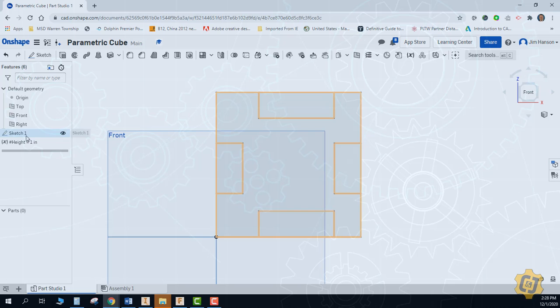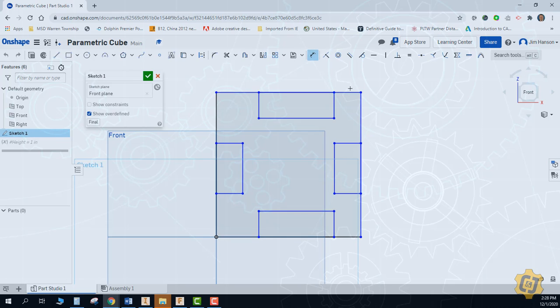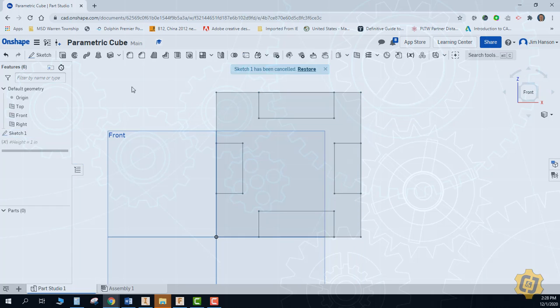The problem is, as I go back into the sketch and try to put on a dimension for the height, it's not usable. It's not something that's been assigned yet. It works just like it does in regular programming. Because this variable's been assigned after the sketch, then it can't be used in the sketch. So I can just grab it and drag it above it.